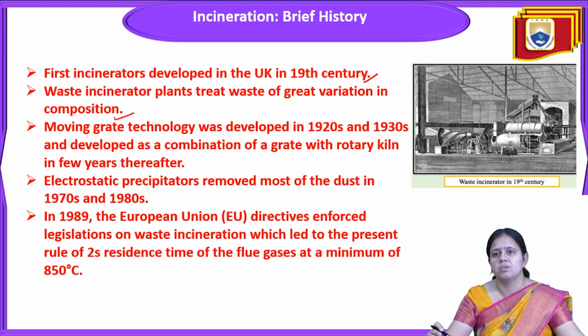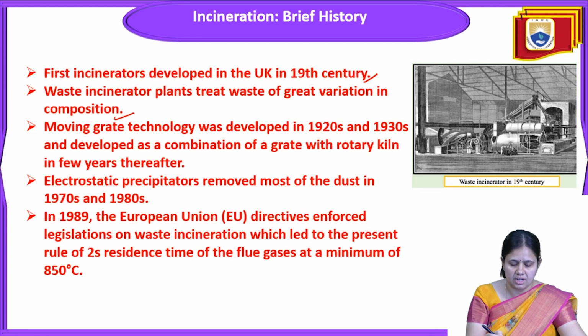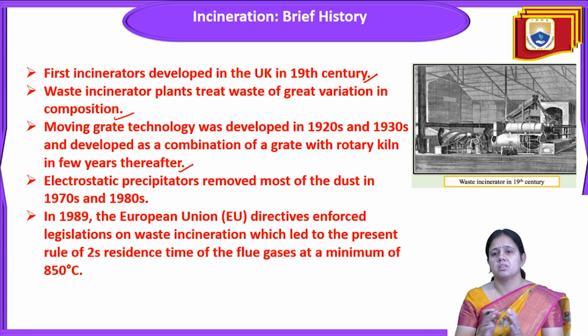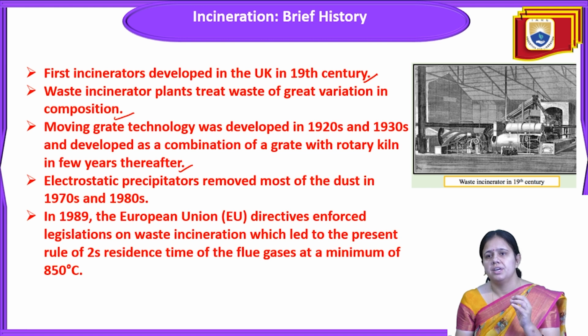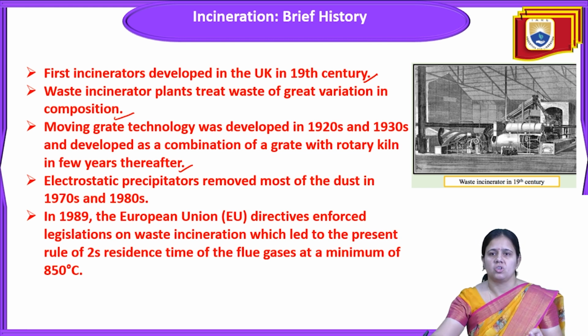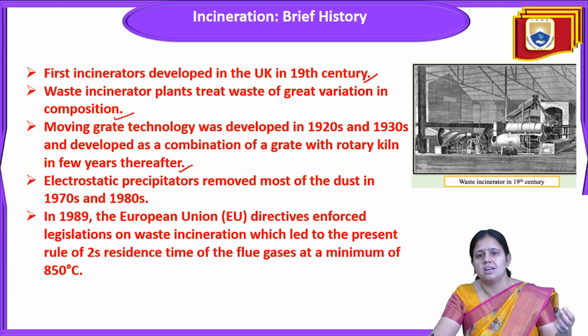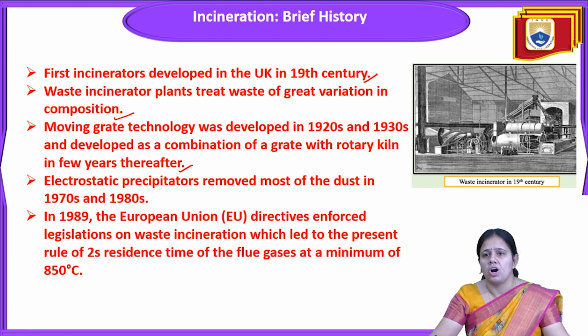Moving grate technology was developed in the years 1920 and 1930, and it was developed as a combination of grate with the rotary kiln a few years thereafter. The electrostatic precipitator was introduced to remove most of the dust in 1970 and 1980. In 1989, the European Union (EU) directive enforced legislation on waste incineration that led to the present rule of a 2 second residence time of the flue gas at a minimum of 850 degrees Celsius.